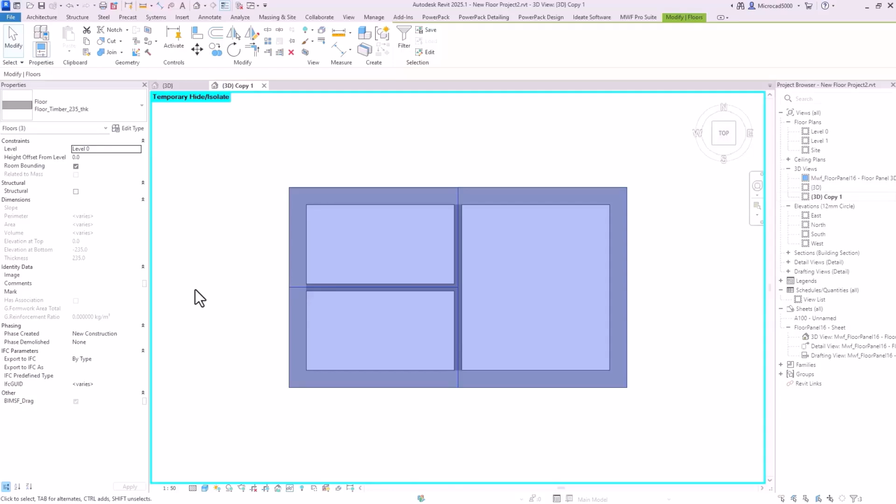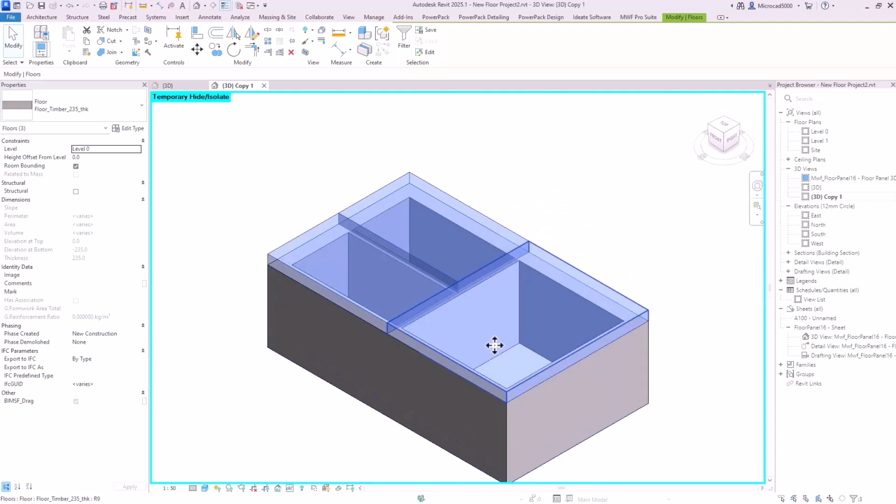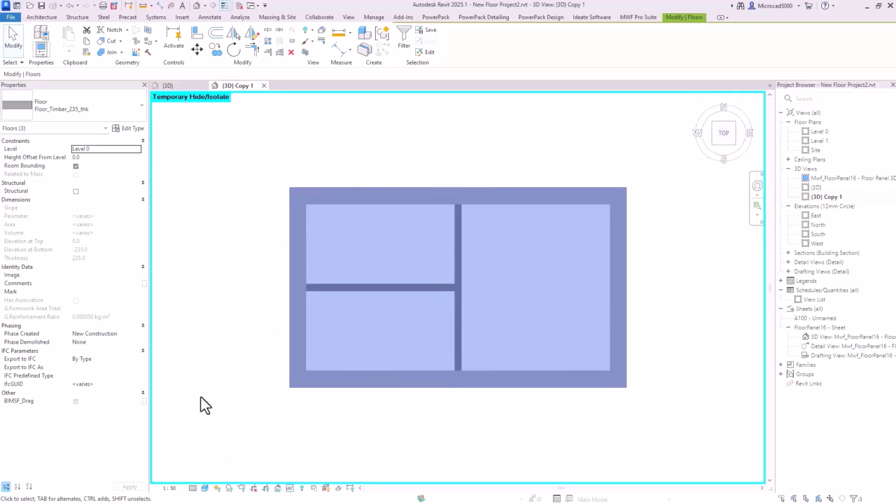We're looking at the MWF Strucsoft framing software to do this. Now you need to make sure that those floors are supported, and as you can see here, yes they are. So I just flip into 3D quickly. You can see here this one is supported by the walls, and it oversails halfway across those internal walls as well. It can also be supported by beams as well. If I put some beams across underneath it, that will be taken into consideration in the analysis.